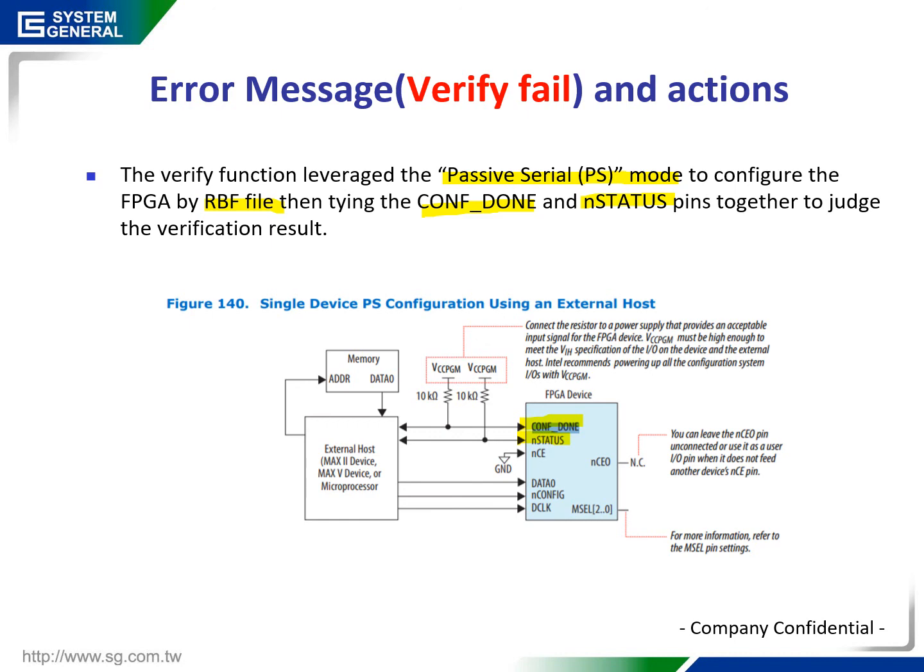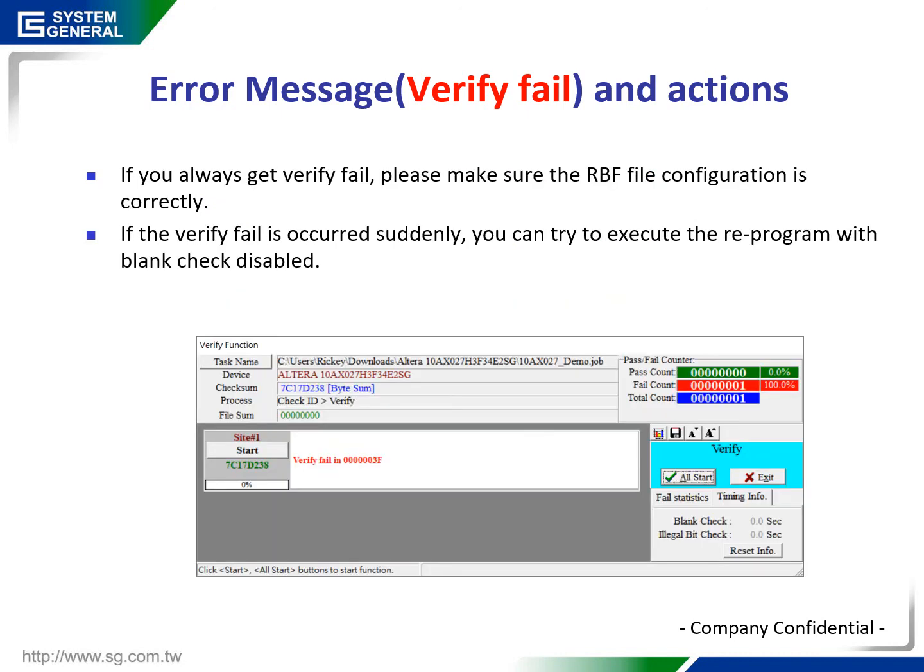If you get a verify fail and you can ensure your RBF file is configured correctly, then it means that the design security key might not match with your RBF file. So if you always get verify fail, you need to ensure the RBF file configuration is correct, and you also need to ensure the RBF file matches the design security key.